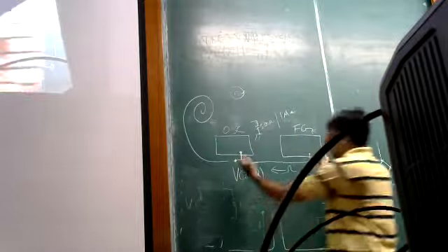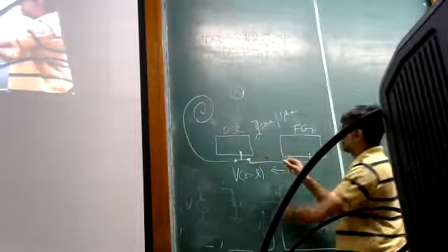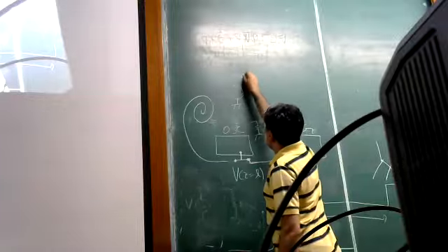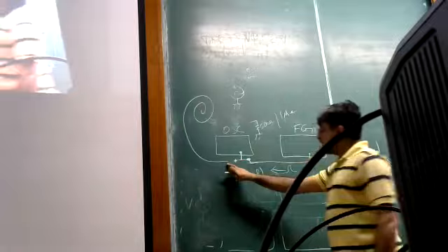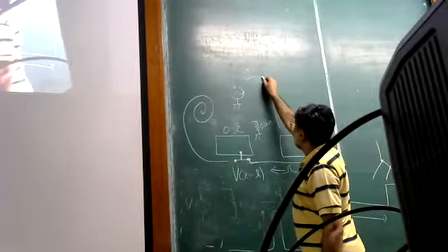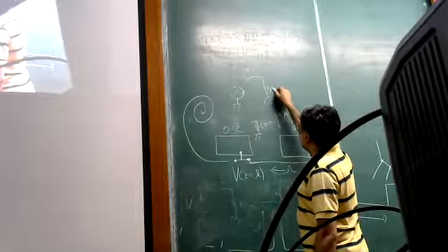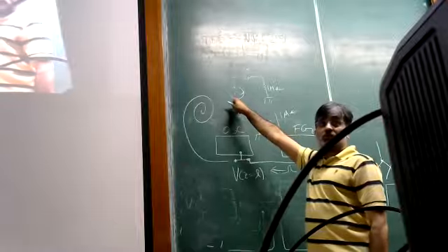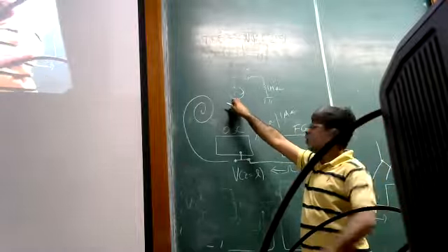So if we sort of ignore the time aspect and the length aspect of the cables for just a second, just to illustrate the point which Gaurav is making, the source is a 50 ohm source. Okay, so this is 50 ohm. When this cable was not there, all it saw was a mega ohm load, and hence it measured the true voltage which is generated here, which is twice of what is mentioned on the screen. So that's why it's 2 volt.